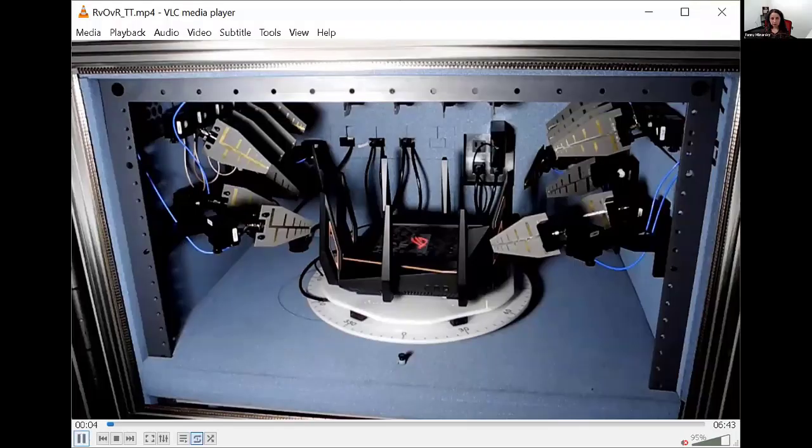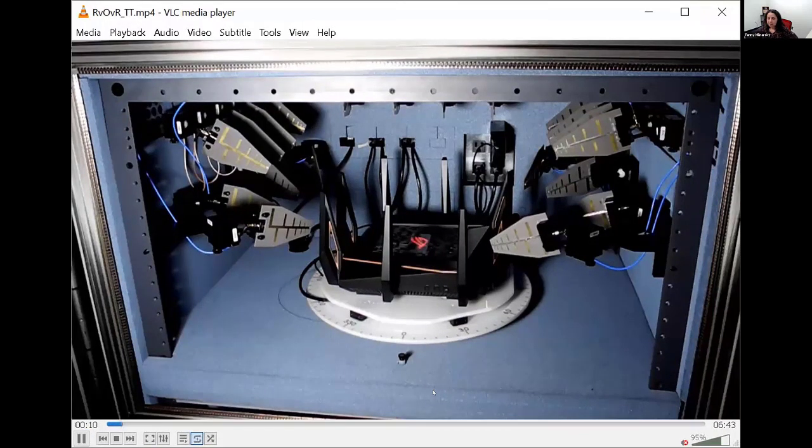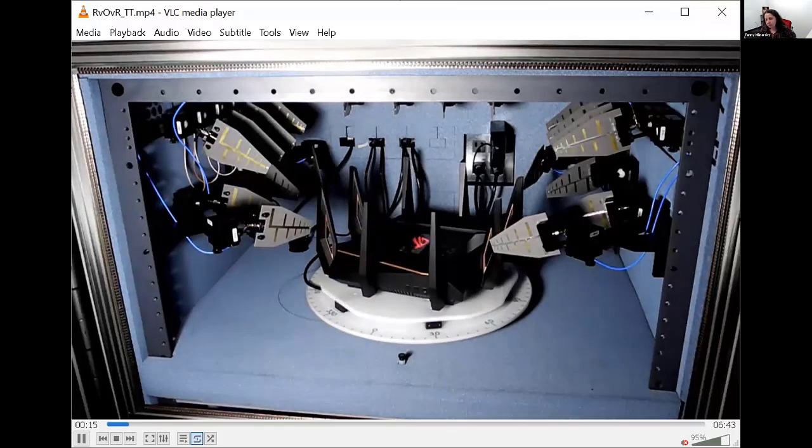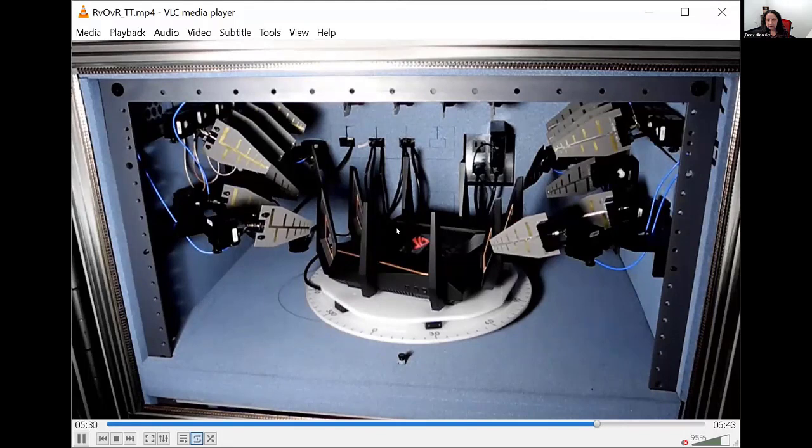So we now have a question while you're playing it. Can we do 900 megahertz range? The answer is yes, we can. Anything down to, well, we like to say 700, but we have customers using it down to 600 and lower, even at 300 megahertz. You just need different antennas. These high gain antennas you see here go down to 2 gigahertz, but we do have other antennas for 900 megahertz range.